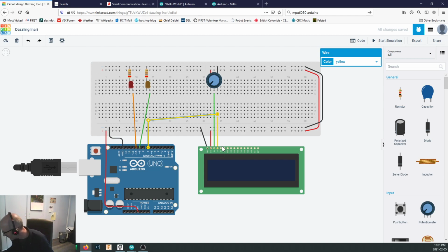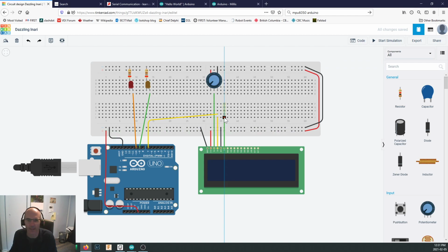Now our next line is the read-write line, and because we're always going to be writing to the Arduino, we don't need to change it back and forth. We can just put that into ground, set that black so it's at ground, and then our next line in blue right here, the enable line, is going to come up here, and I'm going to make that line blue just because that's the way it is on our big bad breadboard board.